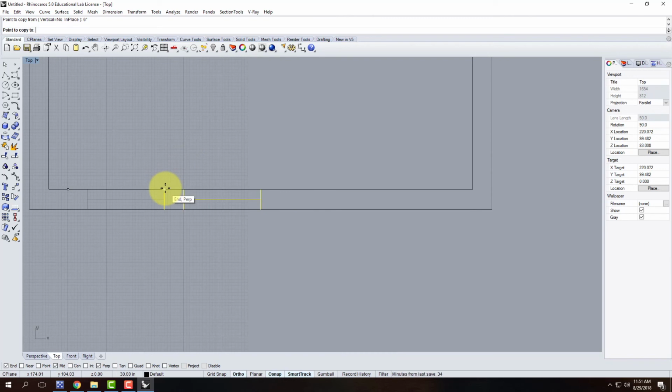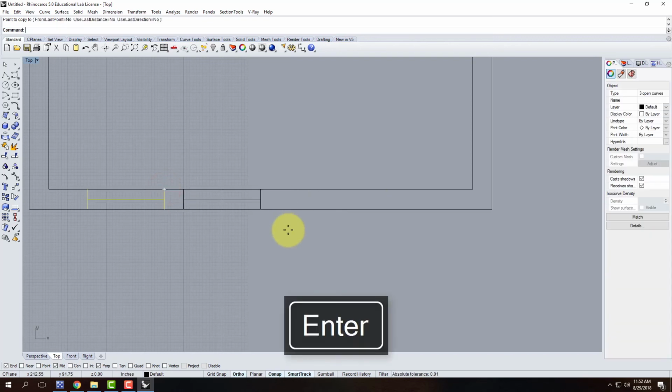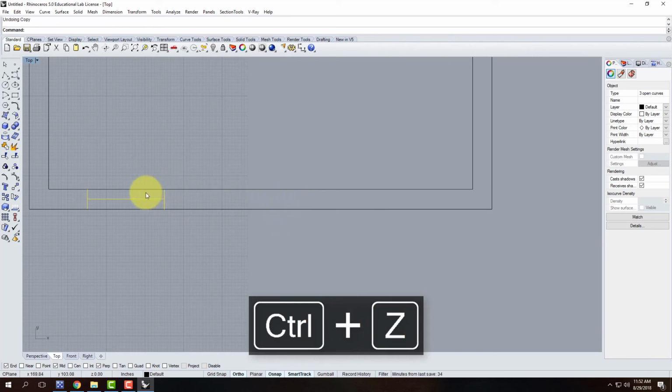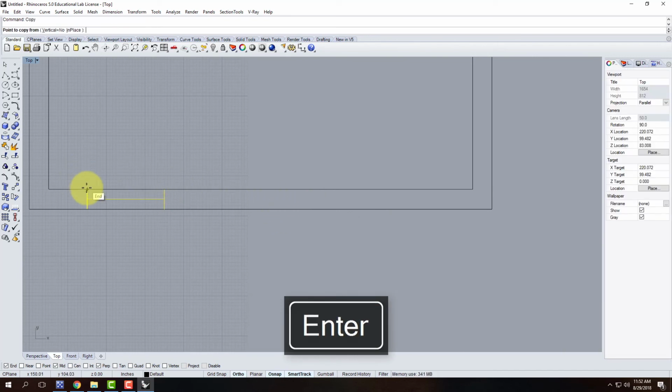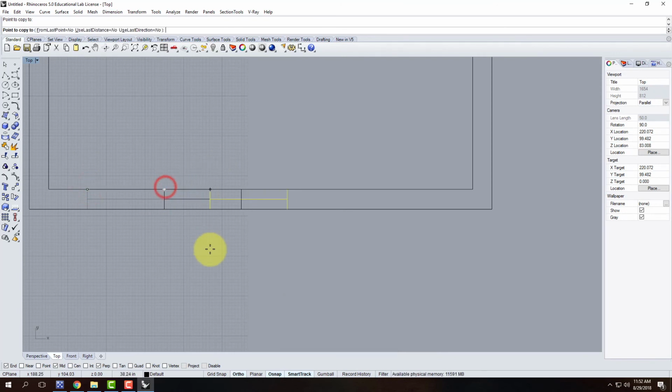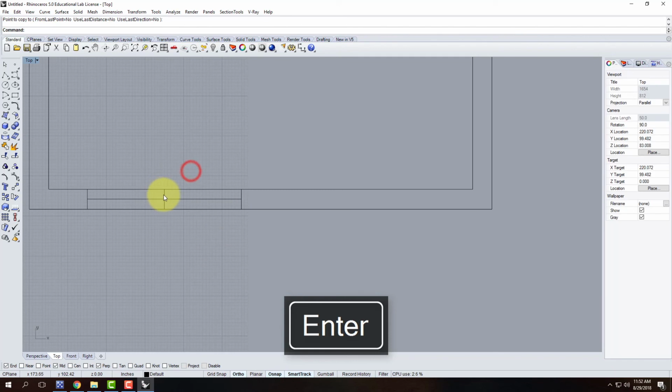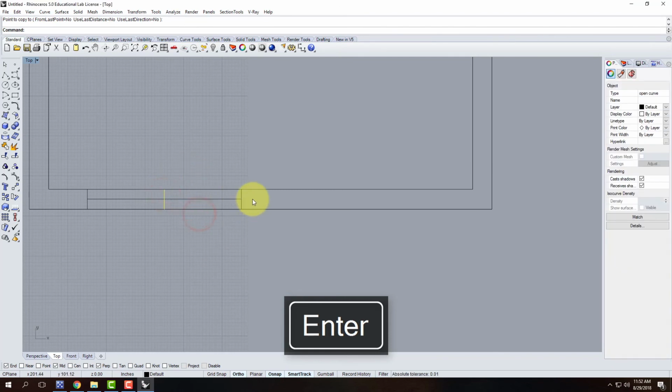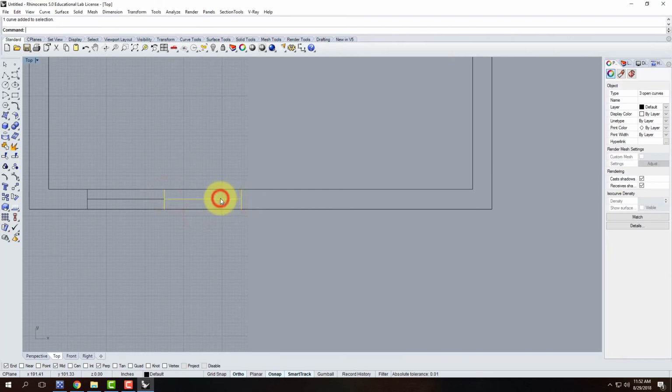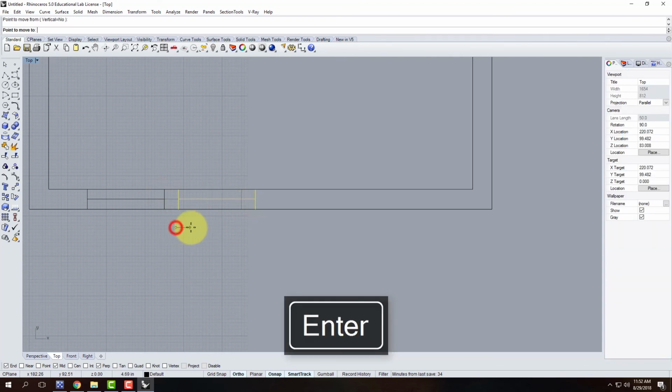It takes a little bit of thinking to anticipate where do you want to copy from and to. If it didn't work, if you didn't think of it correctly, you can always move it afterward to be 6 inches apart. So in that case, it worked. If it didn't work and I said, you know what, let me just copy this, and I said, I'll copy it from right there, and you say, well, I'll put it there. Well, that didn't quite work. Let me take it, and then I could move it by 6 inches, like that.